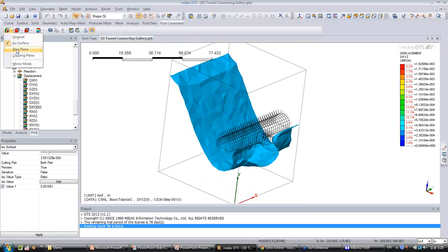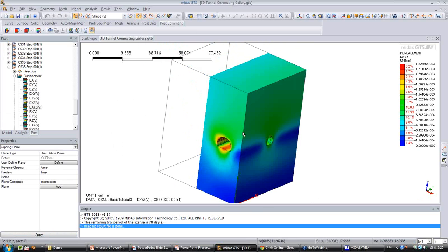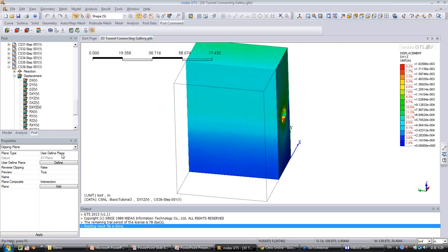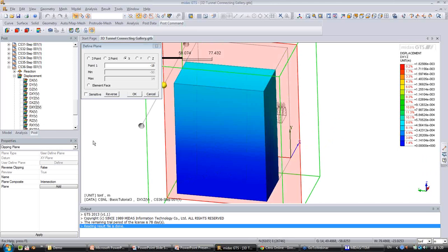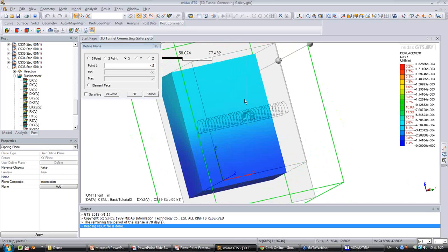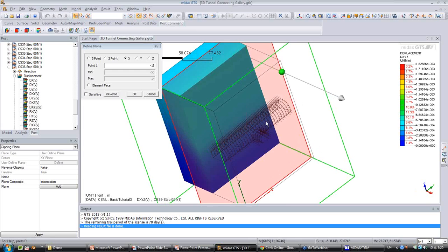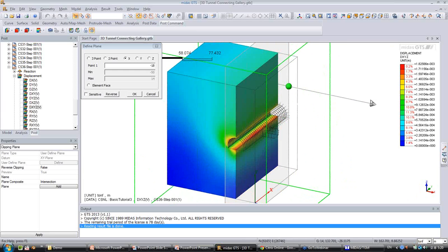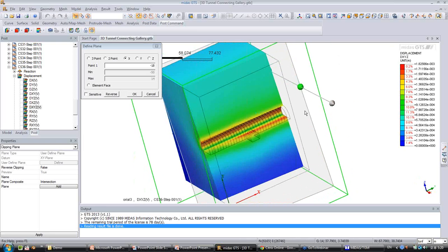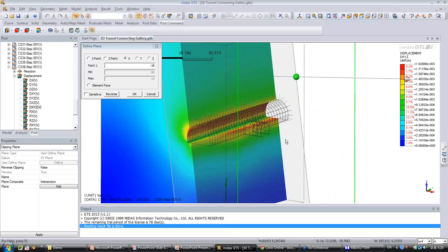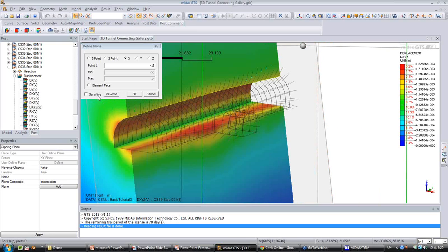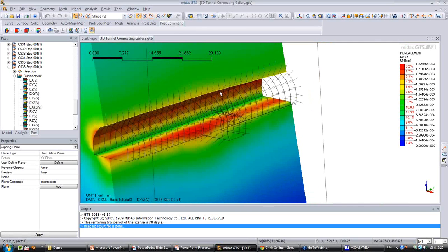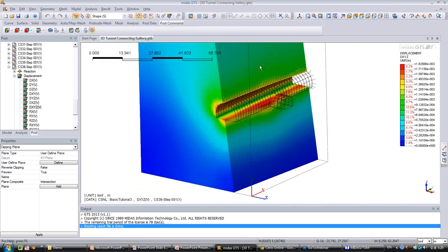Now you have the clipping plane in order to cut a section of your model. Like that, you can drag and drop this clipping plane, so you know exactly where you want to cut and view better inside. So here I have a view inside of my tunnel.